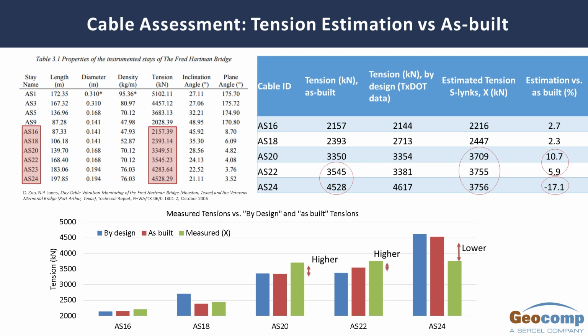Of course, in order to estimate and come up with a conclusive result, whether or not the cable is overtensioned or low, you need to look at more cables and then symmetrically evaluate the structure. In this case, by just looking at these 3 cables, our initial assumption was that maybe one of the cables which lost tension could have its loads carried over by the other 2 cables. But it's yet to be verified, of course, with more cables.